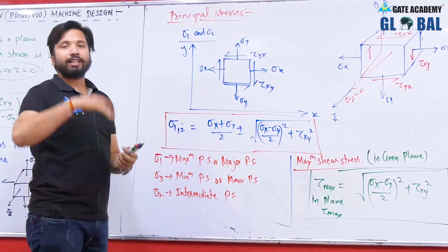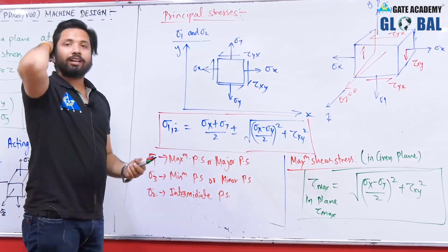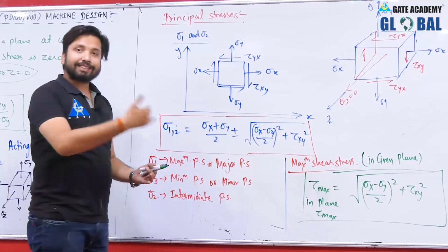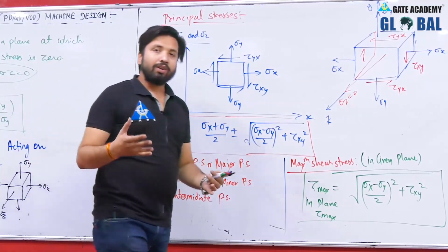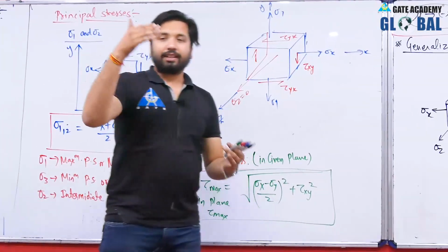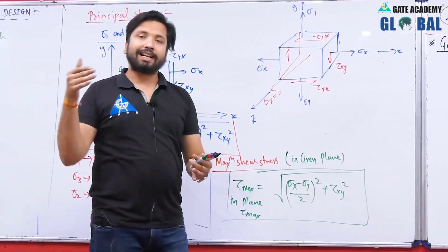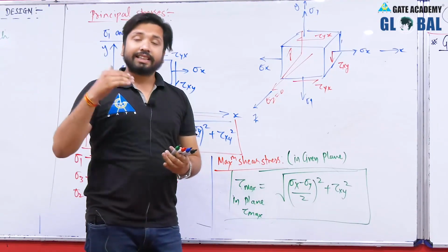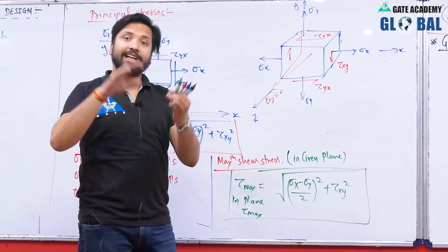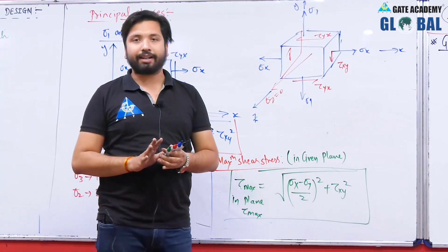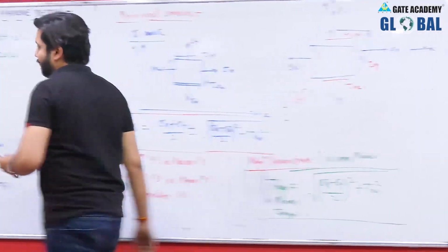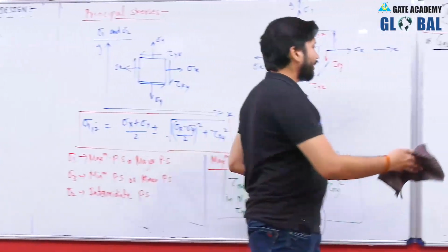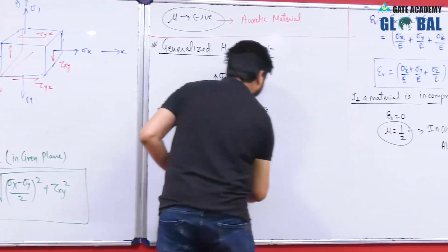If you take the yz plane, then the value of maximum shear stress will differ from this value, and also in case of zx plane, the value will be different. Now, among these 3 values, that is the shear stress in xy plane, yz plane and zx plane, there will be a greatest value of the shear stress, and that is known as the absolute tau max, that is the greatest shear stress present in the element. Let us talk about the absolute tau max, and it will also be part of the discussion in the Mohr circle for 3-dimensional state of stress.